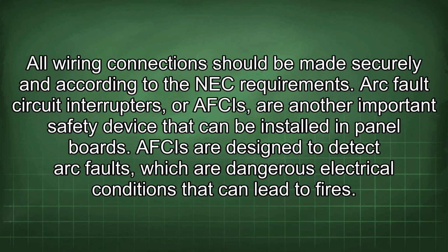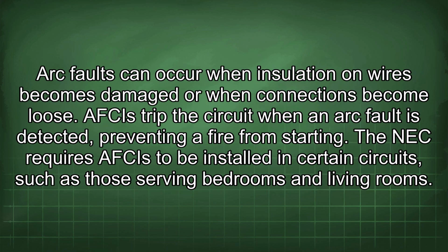Arc fault circuit interrupters, or AFCIs, are another important safety device that can be installed in panel boards. AFCIs are designed to detect arc faults, which are dangerous electrical conditions that can lead to fires. Arc faults can occur when insulation on wires becomes damaged or when connections become loose. An AFCI trips the circuit when an arc fault is detected, preventing a fire from starting. The NEC requires AFCIs to be installed in certain circuits, such as those serving bedrooms and living rooms.